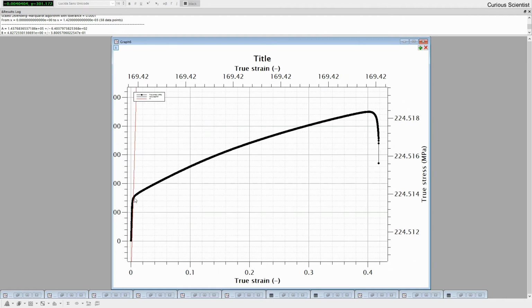You can take a point between the yield strength and roughly the maximum strength and fit a higher order polynomial on this curve, and then if you differentiate the polynomial, then you have the analytic function. So that's very straightforward. You can even do it by hand, but then the derivative curve will be nicer, but maybe that's not so nice. I don't know which is better.